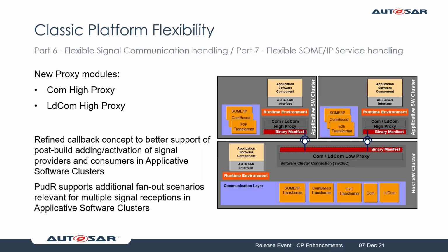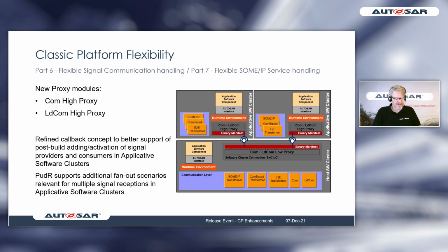We always have the signal-based communication through the COM module, and we have the SOME/IP service-based communication via the large data COM module. Both are now also provided as a high proxy module to have an optimal support for the external communication also in these software clusters. This is, for example, essential if a signal is received in multiple software clusters. So we need to distribute this to multiple software clusters in the most efficient way. And therefore, features are added to the PDU router and so on.